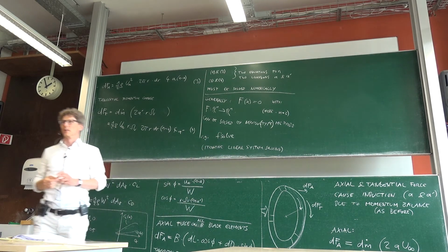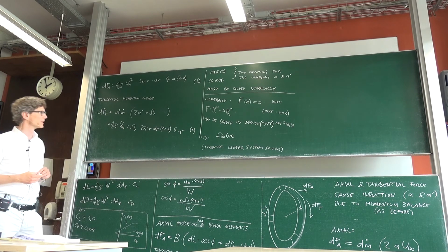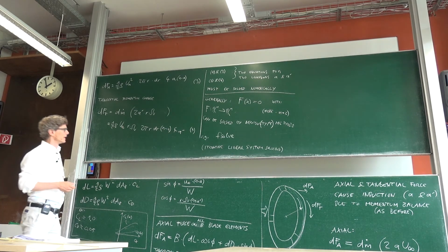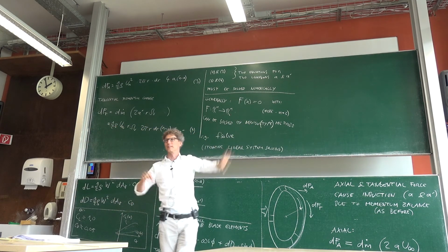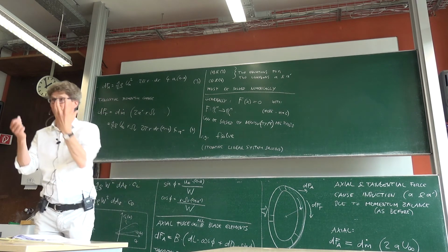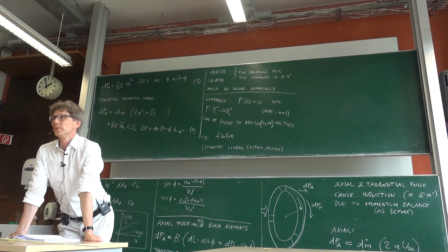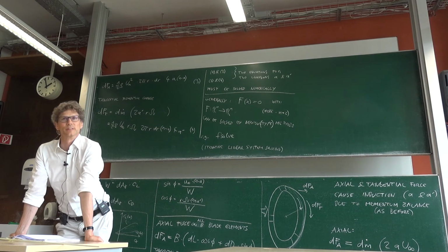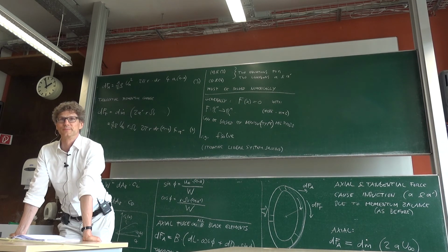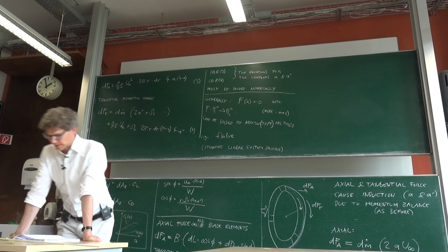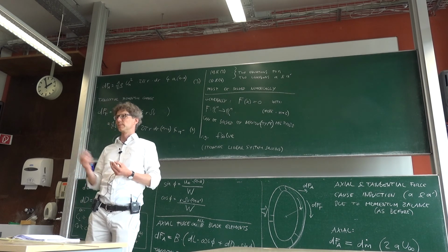Okay, and our main task from our perspective is not to write such a Newton-type method for solving. That's something we can use, but our task as wind energy engineers would be to formulate the residual function big F in a decent way, so that it depends on the things that we want to know, namely a and a prime. So this would be a long computer code for this function F, but once you have it, you can pass it to a root finder procedure like fsolve in MATLAB, and then you can go to a solution. And at the end, it doesn't feel so different from just evaluating an exponential or a sine function on a computer, right? It's just some root finding procedure.